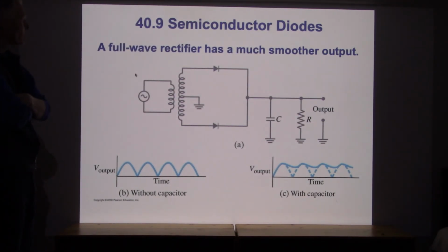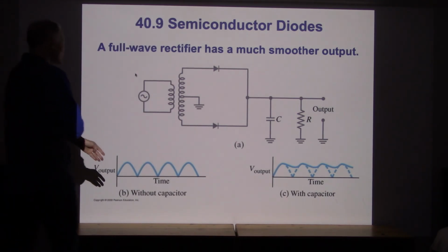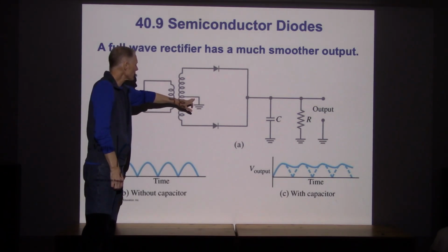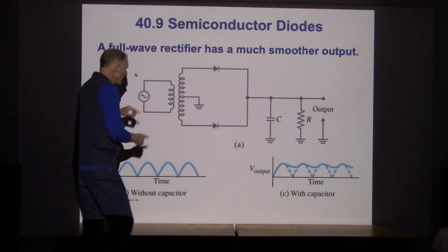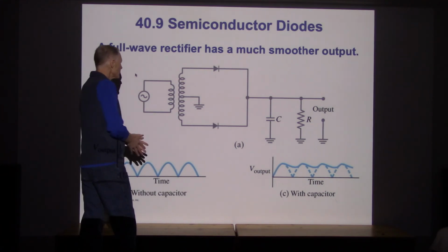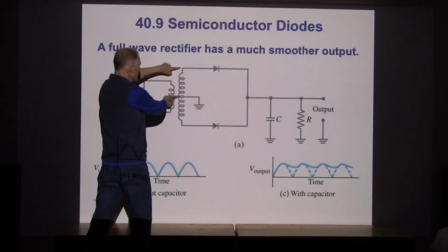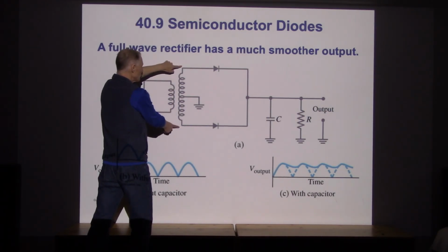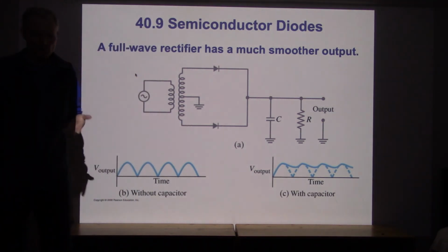Now, this is actually how houses are hooked up. There's a neutral wire inside the wiring inside houses, and it's set up like this, and then you end up in standard electrical hookups for houses and buildings. You have 120 volts here, you have 120 volts here, and across here you have 240 volts. So the transformer itself is set up to enable a difference of 240 volts.